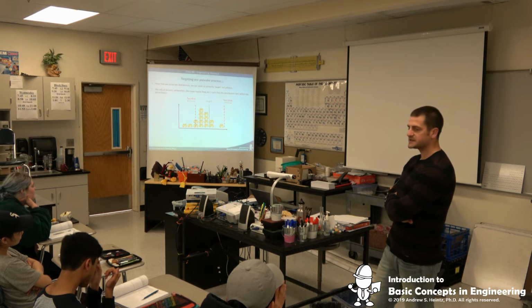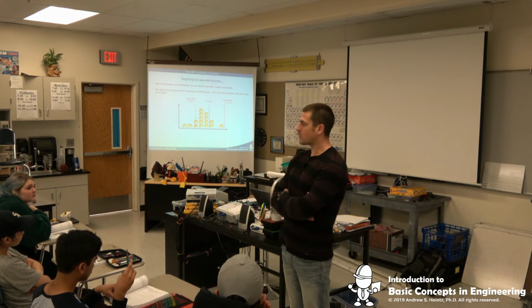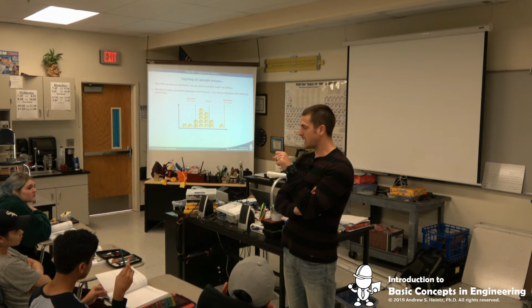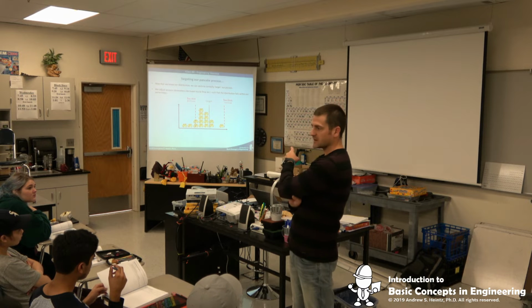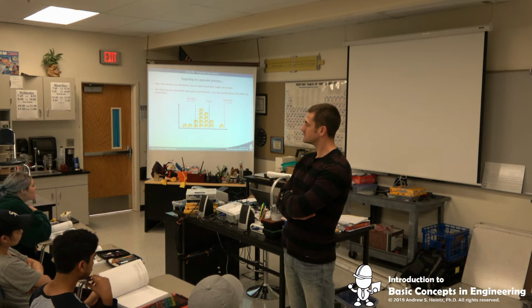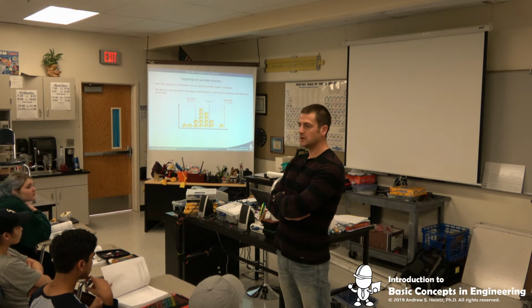So in this case, let's say we're creating our pancakes by doing a 4-second dispense, right? So 4 seconds of batter, 4 seconds of batter, 4 seconds of batter, 4 seconds of batter. This is telling us what? 4 seconds is way too thin. Is a bit too thin. Yeah, 4 seconds is not enough time, right?